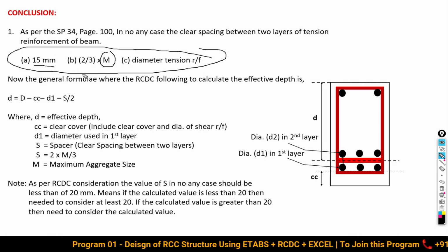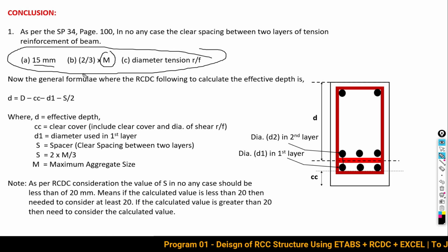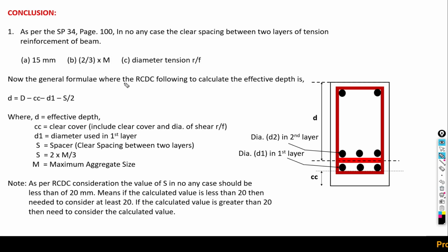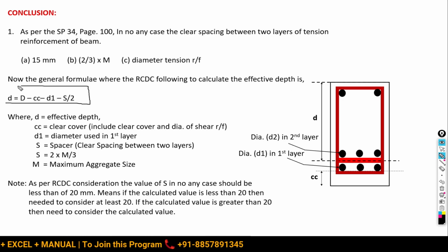So amongst these all three, in most of the cases, most commonly the greater value we will get from this second option. So next, now the general formula where RCDC is following to calculate the effective depth. So RCDC is following this formula for calculating the effective depth.